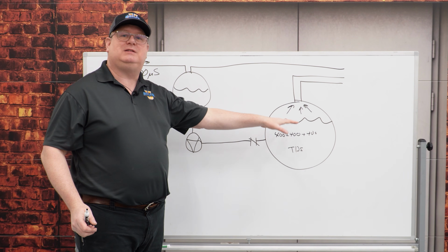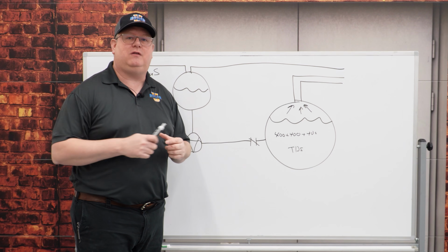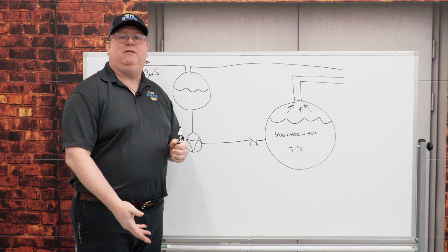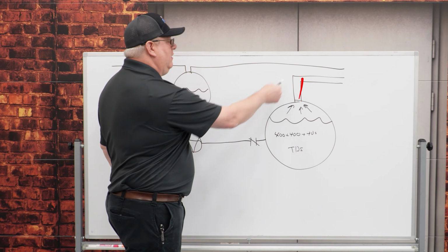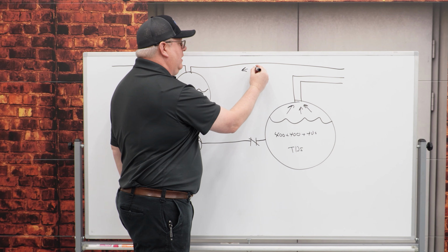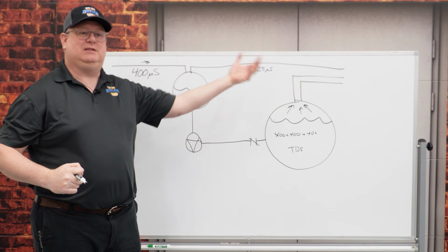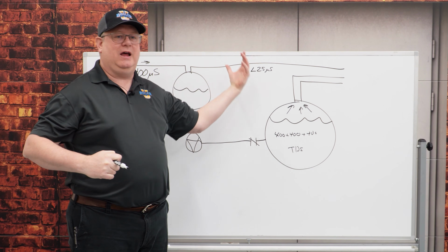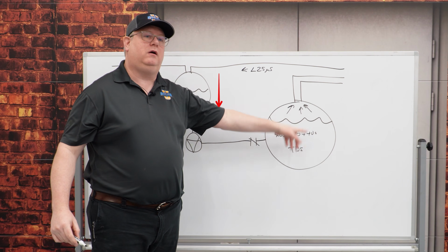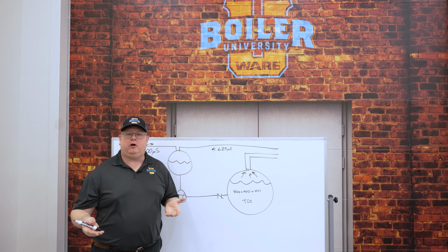If your boiler doesn't cycle up, and you are generating steam and sending it into the system, there's really only a couple ways that water could be leaving, because essentially steam's leaving into the system that's pure. That condensate coming back from the steam system is usually less than 25 microsiemens of conductivity because it's distilled water, because it was steamed and condensed. So eventually our feed tank number could come down a little bit, but our boiler really won't. The only way it can is if water's discharged from it.